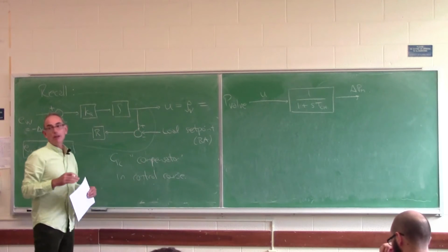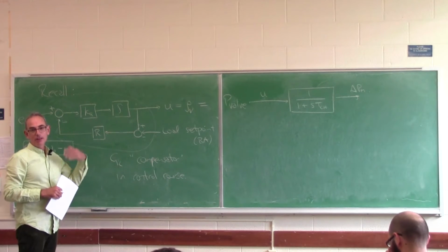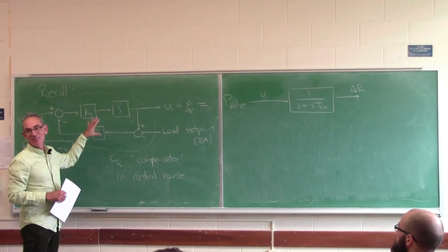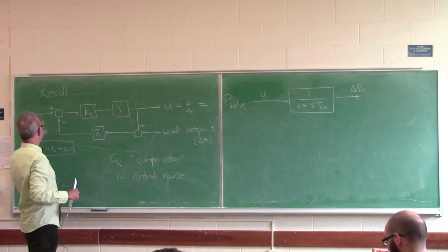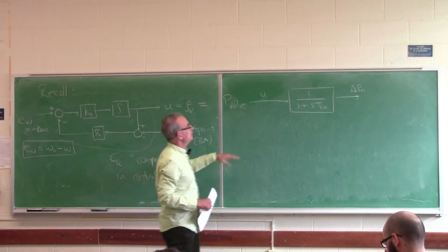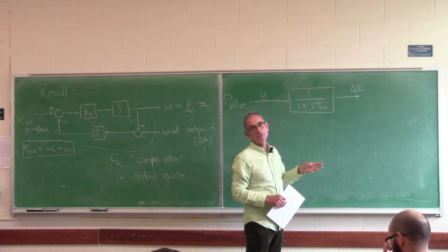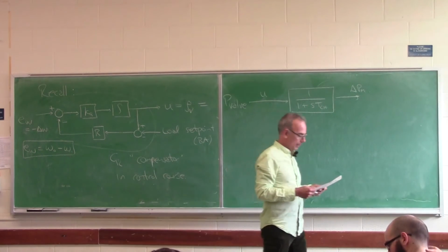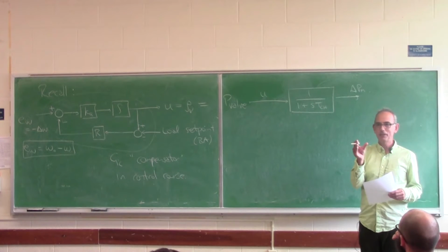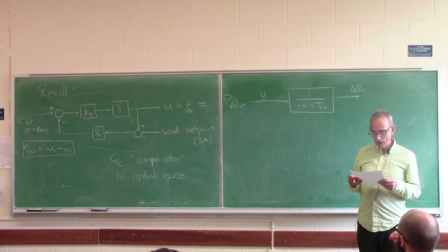And that's the main thing that makes control a difficult subject, is you often can't tell what is physics and what is in a computer. So this is on a computer. This is something where you're making decisions. Based on the error signal, you're making a decision on the valve angle. And this is a crude approximation of the physics of valve position to power. And it's natural to be a low-pass filter because when you suddenly change the valve angle, you don't instantly change the power. There's some ramp-up time for it to change.